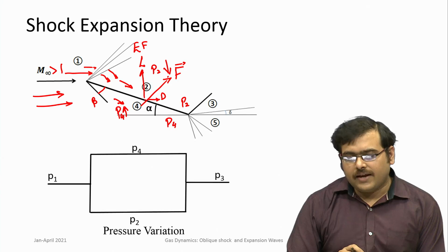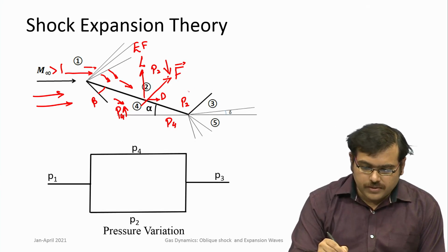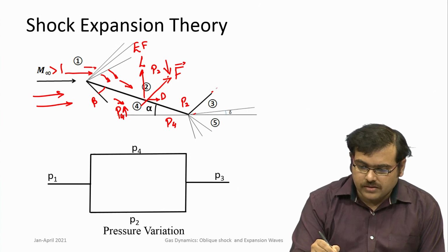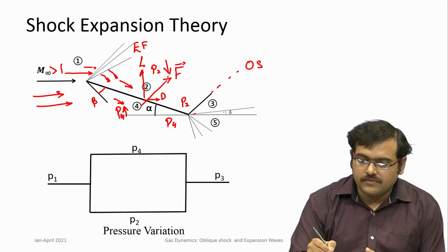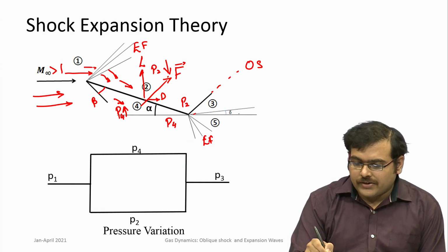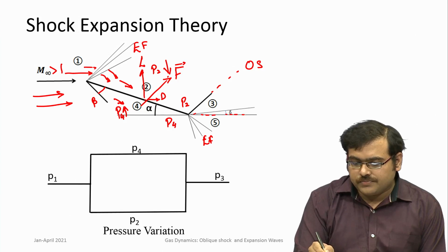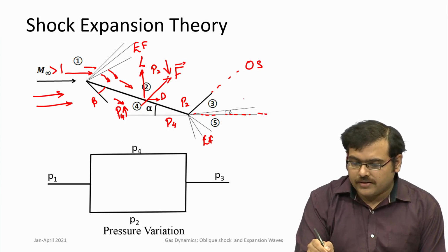As a consequence of that, you get additional wave forms at the trailing edge. You get a shock here because the pressure is lower, so it has to get compressed. There is an oblique shock that gets formed here, and at the bottom surface you have higher pressures and the pressure has to be relieved, or it has to get expanded. You get expansion fans here, and you get a slipstream, essentially a surface which demarcates the boundary at the trailing edge between the upper surface and lower surface.